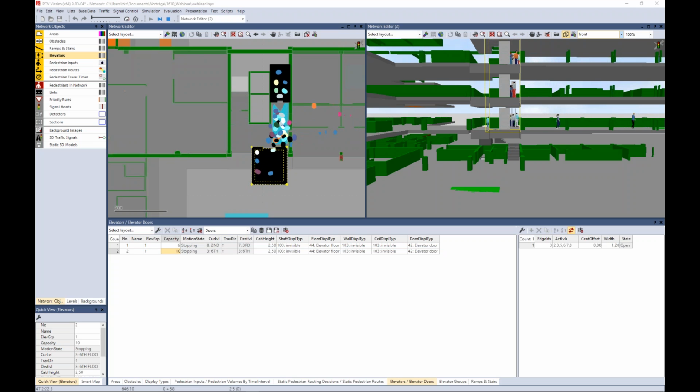So it serves all calls, all demand in the current movement direction until there is no more demand in that direction, and then it turns around. And if there is nothing to do on a particular floor, it does not stop, so it continues moving. An elevator which stops on each floor would be the so-called Sabbath algorithm, because it's forbidden to operate a machine on Sabbath for Jews, and there the elevators are in Sabbath mode on Sabbath.